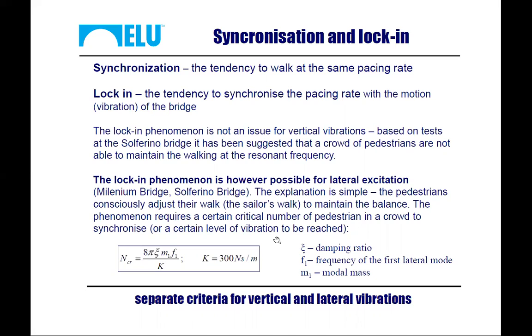Of course, when we are talking about lock-in, it's not enough to have just one person walking in synchronization with the bridge motion. We need a critical number of pedestrians that will generate a motion large enough to be felt by everybody and start being a synchronization signal, if you want.